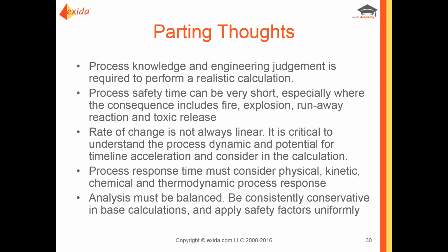If you've got any kind of trip delays or lags, they also need to be considered as part of that. Delays within the SIF itself need to fit into that SIF response time. Delays in the process, initiating or following, need to be considered outside that SIF response time.